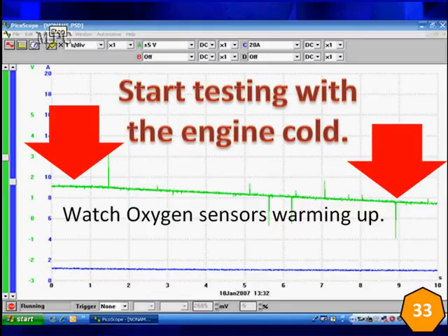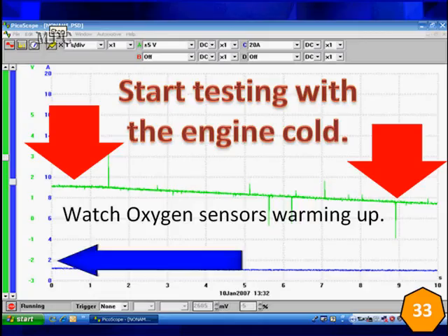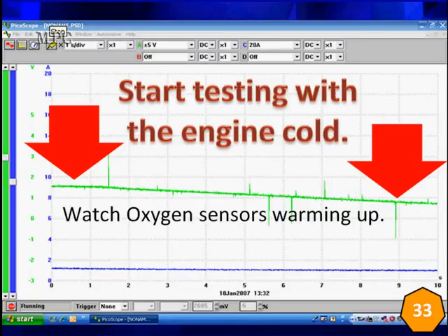But I want you to look at something here on this lab scope. First, we're going to identify a few things. We're looking on the green scale at a 1 volt signal. As soon as we start testing, we find out very quickly we need to pay attention to what's going on. Now, I want to talk about the scales. Look on the left side of this. The blue writing is for the amperage. Our blue trace is between 0 and 2. That's just slightly above 1 amp.